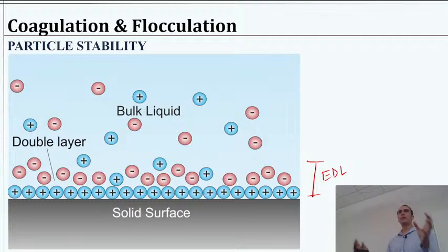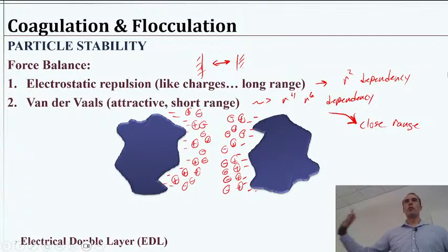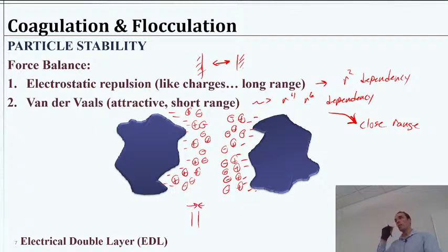We left off talking about this effect that particles and surfaces have in water, where the charge of some surface can extend out and push other particles away, typically because they're both negatively charged. So it's kind of the stiff arm approach. We did a little diagram showing the particles repelling each other until they get close enough, and then the attractive forces outcompete the repulsion forces, and they stick together, and the ions tend to get out of the way a little bit.